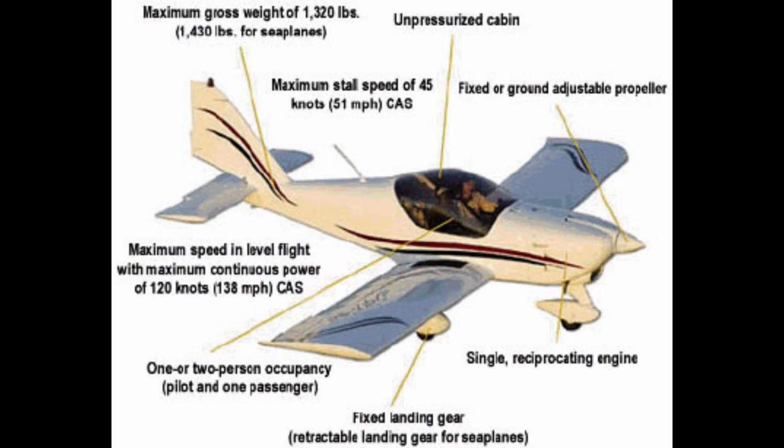Aircraft engines and propellers can be manufactured one at a time from the design drawings, or through an FAA-approved manufacturing process, depending on the size and capabilities of the manufacturer. During the manufacturing process, each part is inspected to ensure that it has been built exactly according to the approved design. This inspection is called a conformity inspection.